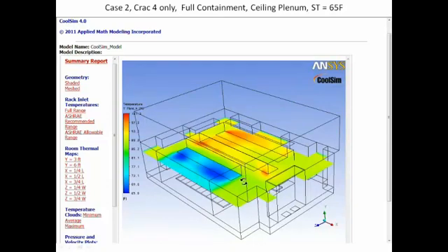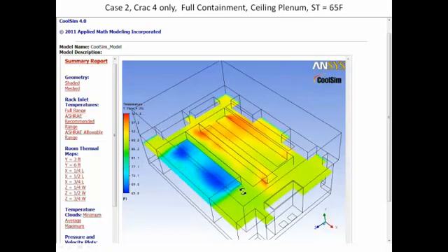Because you invite somebody into that data center and they're effectively walking into the hot aisle return. Hot aisle returns running near 100 degrees tends to make people a little nervous. Yeah, right. And then you have the combination of servers with very high delta T. Yes. That can really drive, especially if you have relatively high inlet temperatures to the servers, then you get exceptionally high temperatures on the return side. Yeah. Right, that's very, very true.